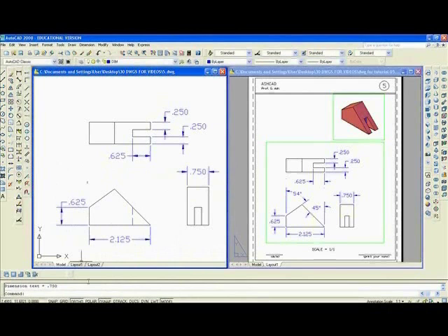You will remember that if I want to fix that, I'll have to take off Object Snap, take off Ortho, click on it, use the grips to move it down like that. Now then, in order for you to create an angular dimension, you need two lines. So I'm going to draw a line with the O-snap on, ortho on, from this point up here like that. I'll also draw another line, hit the spacebar again, up here like this.